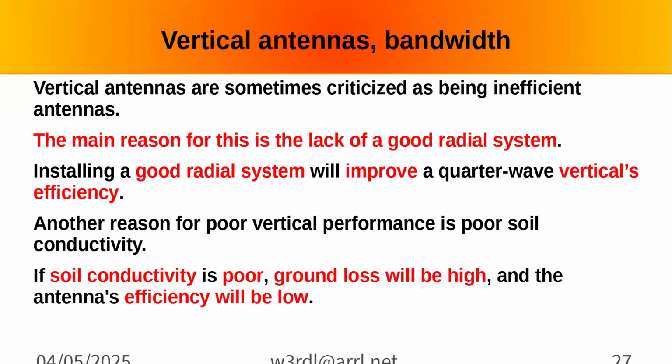If you've ever looked at broadcast transmission, which is where the radial system kind of got developed, and this wives' tale about quarter wavelength for the radials, that's not really true. It turns out because they had lots of money, they did a pattern of radials where the spacing at the end of the radial was 0.05 wavelengths apart.